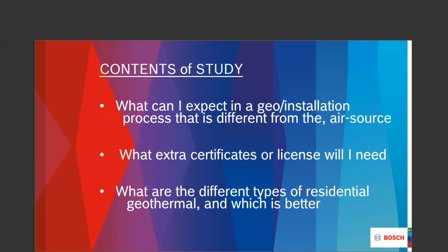The geothermal system in an open loop scenario is going to be looking at a GPM of about 1.5 gallons a minute per ton, as long as the water coming into that system is above 50 degrees. And when we drop below 50 degrees, 49 degrees and lower, then that water needs to be 2 gallons a minute per ton flowing through that machine. So you've got to have some water quantity.